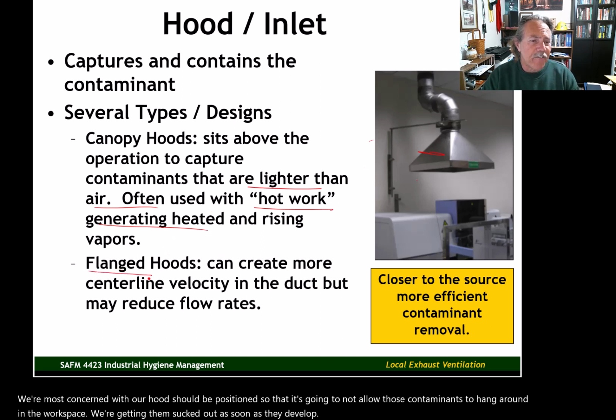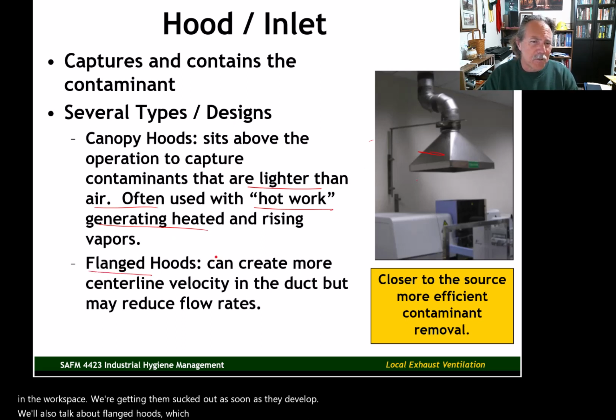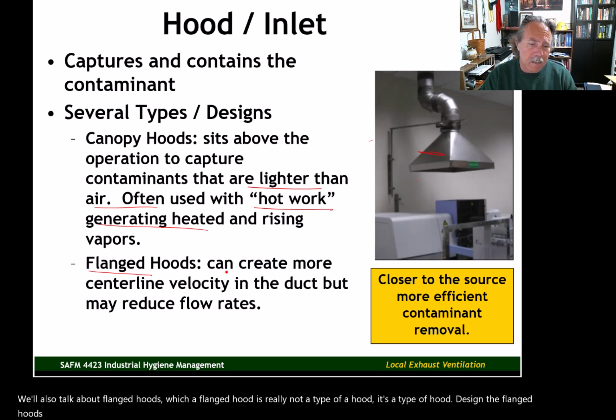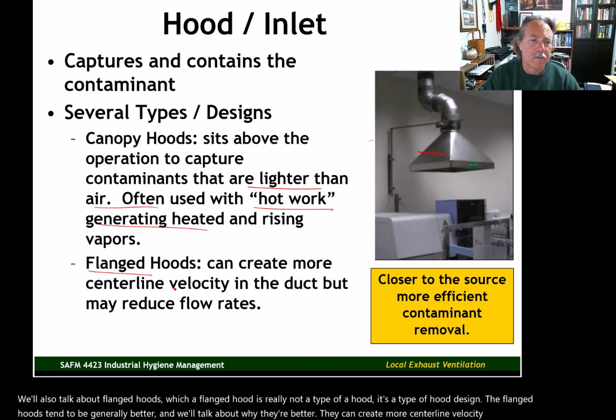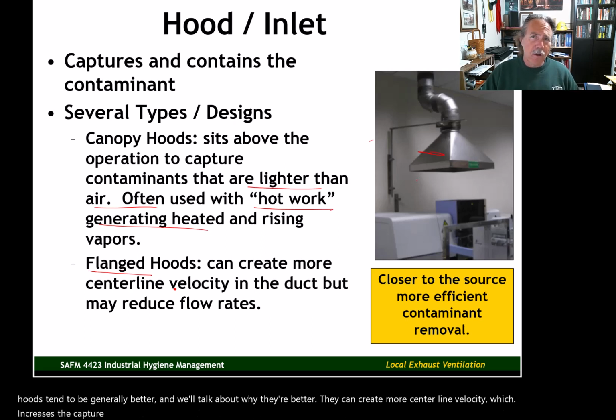We'll also talk about flanged hoods, which is really not a type of hood. It's a type of hood design. Flanged hoods tend to be generally better, and we'll talk about why they're better. They can create more centerline velocity, which increases the capture capabilities, or the capture velocity, of your system.